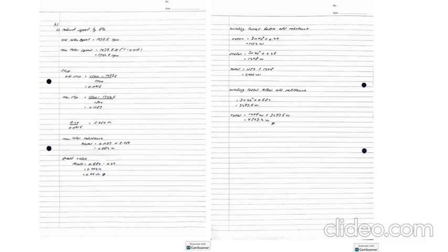5.769. And after that we calculate the new rotor resistance, the R total. 0.1183 from the new slip, we multiply with the latest resistance, which is 5.769. From this R total we got around 0.682. After we calculate the R total, we need to get the value for the added resistance, which is the R total minus 0.24.